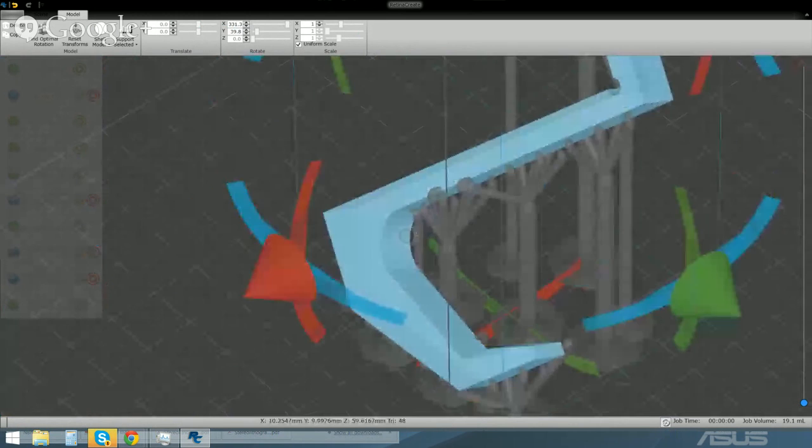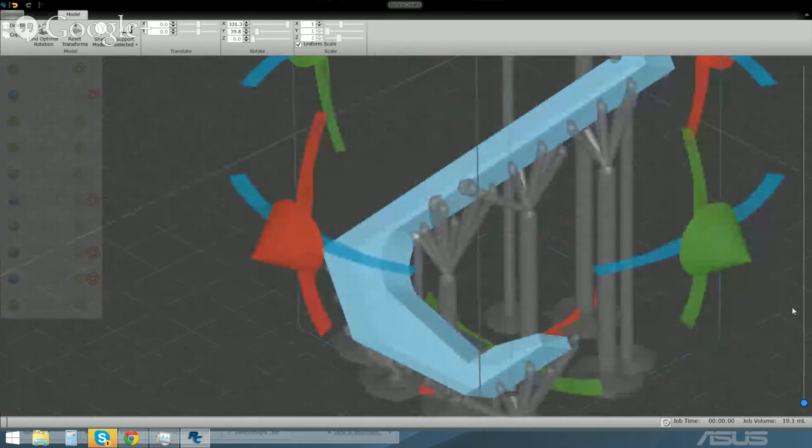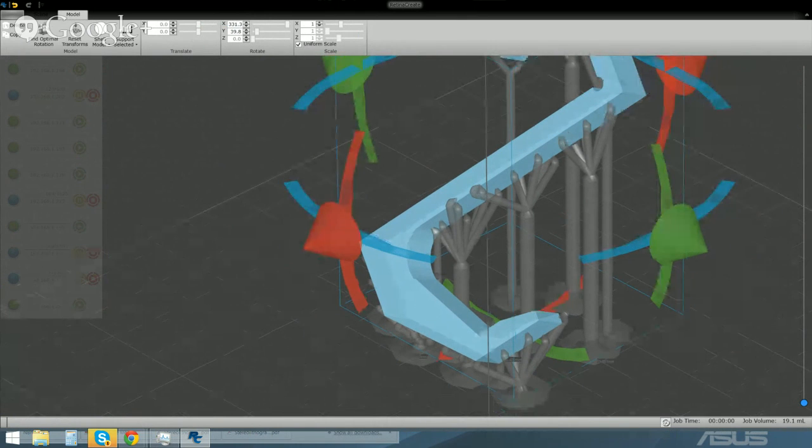And in general, with that, as well as the tree supports, the automatic support generation gets to be a lot better and a lot more reliable. And it's able to properly support more objects, and it wastes less resin as well. But it's still not perfect, and there will be times when, even after supporting it, if you run the model analysis software, you see that there's an unsupported floating part, and that happens.